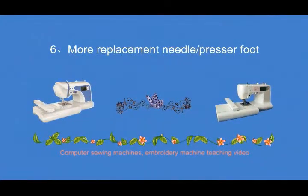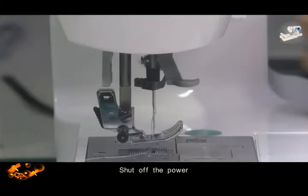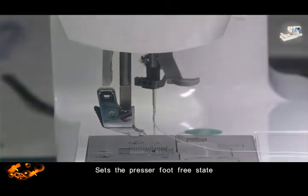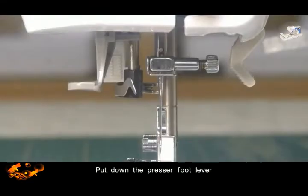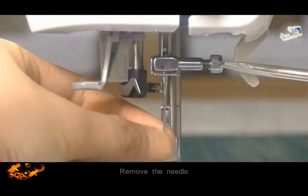Six. Replacing needle / presser foot. Shut off the power. Press the foot spring switch on the shelf. Sets the presser foot to free state. When installing, aim at the presser foot rack slot. Put down the presser foot lever. With a screwdriver, loosen the needle fastening screws. Remove the needle.